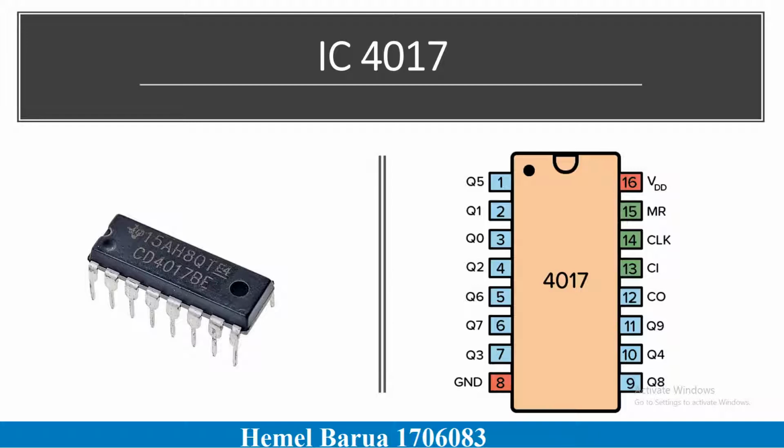In our project, there is 5-way, so we will need minimum 10 outputs, so we are using all the output pins. We provide clock from the output of 555 timer. In our IC 4017, there is a disable pin, which is pin number 13. In the normal mode of operation, this is connected to ground or logic low voltage. If this pin is connected to logic high voltage, then the circuit will stop receiving pulses, and so it will not advance the count irrespective of several pulses received from the clock.